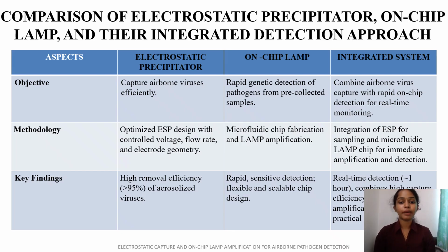Methodology was optimized ESP design with control voltage, flow rate, and electrode geometry. For on-chip LAMP, microfluidic chip fabrication from PMMA, PDMS chips, and LAMP amplification. For the integrated system, the methodology adopted was the integration of ESP for sampling and microfluidic LAMP chip for immediate amplification and detection.